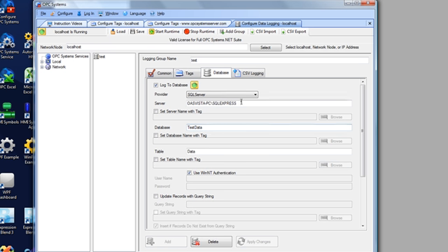Now you're also welcome to include a remote SQL Server or Oracle node using the Oracle client connection to log to a remote database engine and just have local tags. They could also be remote tags, so you could go from remote tags to remote database engine and use it as a pass-through. That's completely valid to do. The reason I say it's okay to also do the remote database connection is because we have buffering that's available for both the data source and the data destination.